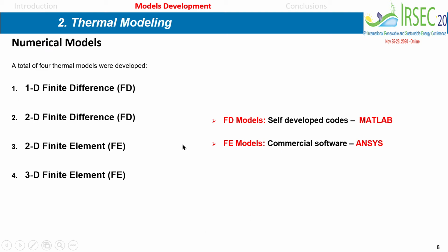So we worked on a one-dimensional finite difference model. Then we extended it to a two-dimensional finite difference. We also use a 2D finite element model, and we use 3D finite element. However, in this work I will focus mainly on the 2D finite difference and 2D finite element using ANSYS code, but he is using our code, which we wrote in MATLAB.